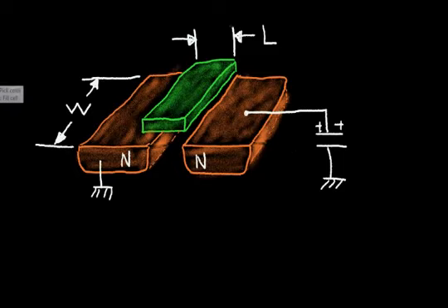So let's review the MOSFET operation just very briefly. Now when I raise the gate voltage relative to the source voltage, I form a channel region in this MOSFET transistor. And that causes current to flow from the drain to the source. Now the key thing I want to point out is that as I make this transistor wider,